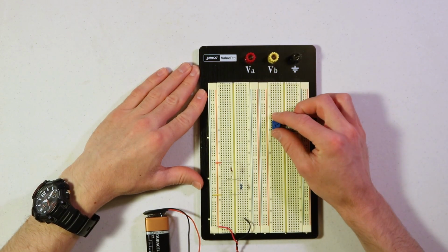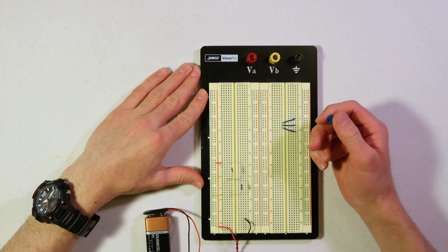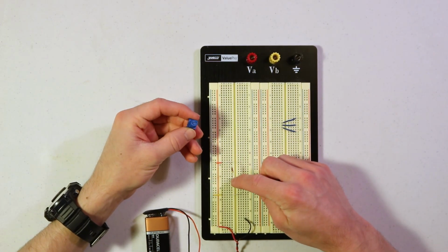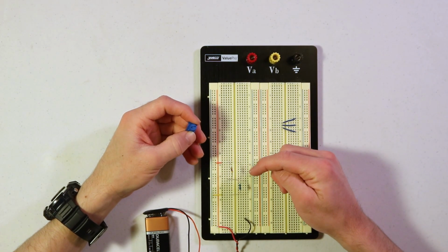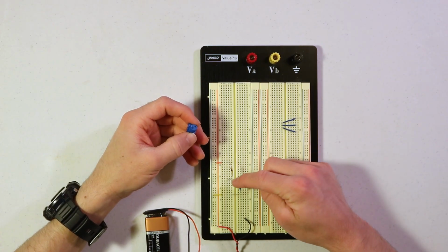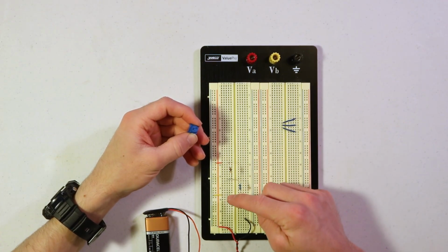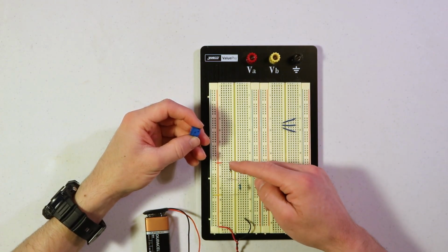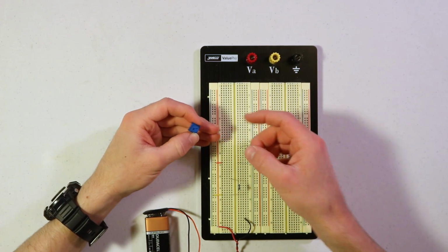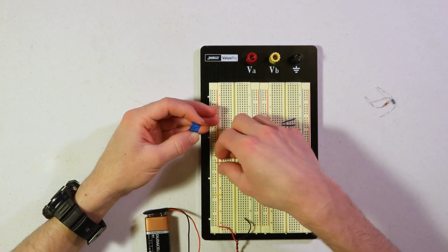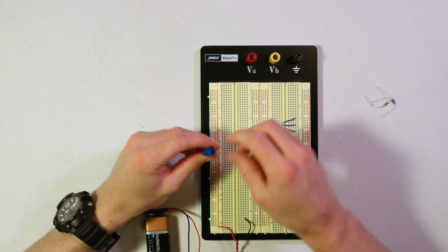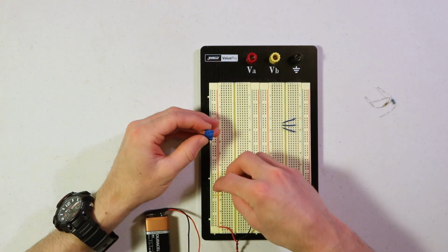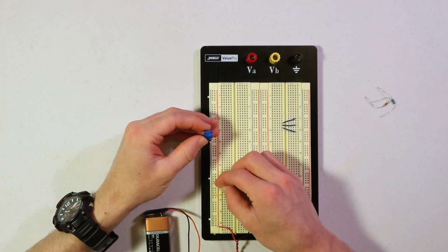Now, like I said, this is very similar to the series resistors that we had from before. The only difference is that now we can adjust the point in between. So now, instead of just having it fixed between these two resistor values, we can adjust it from pin 1 all the way to pin 3, so that this resistance in the middle is going to be dependent on how far we've turned the knob. So let's just remove these two resistors, and then we can place this potentiometer just like we had the two resistors, so that we can have our resistance in between the power and the ground rails.